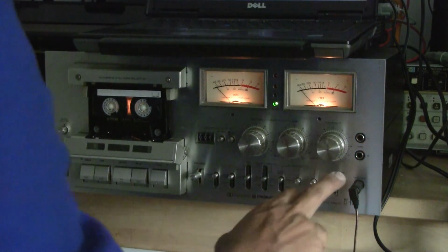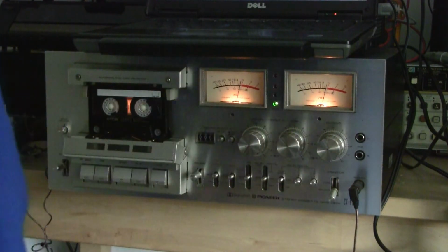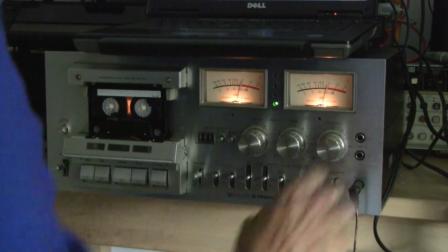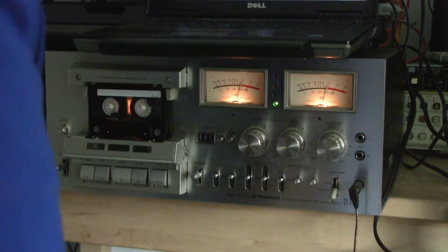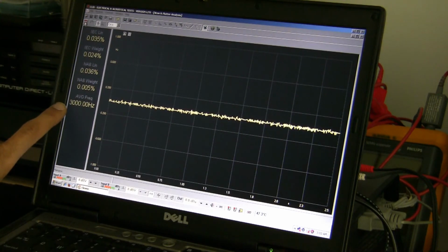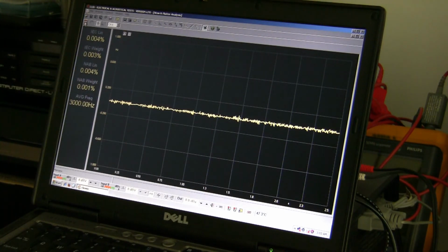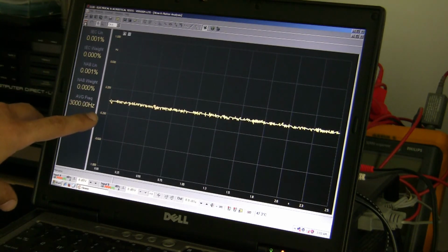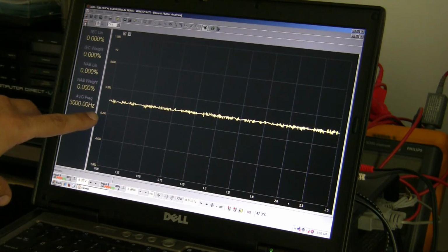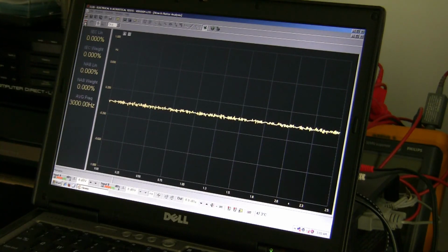We are going to start with the source, and we are going to check if Clio is going to do a great job. We can observe it from the screen. We are generating a 3 kilohertz tone, and Clio is reporting 3 kilohertz, and we are going to wait to see all the metrics converging to 0, and like before, the scale has been adjusted to minus 0.2 to plus 0.2 hertz.